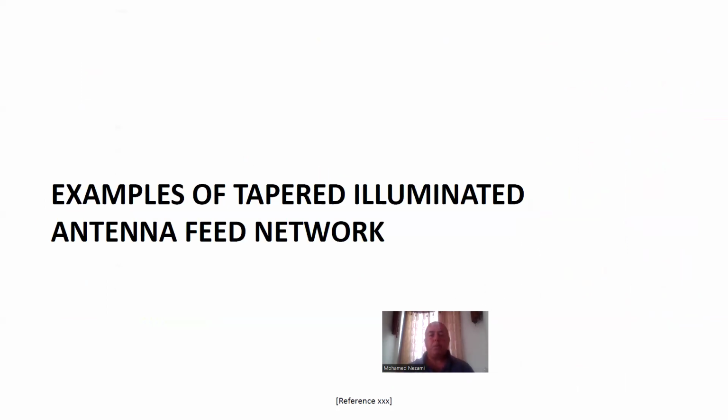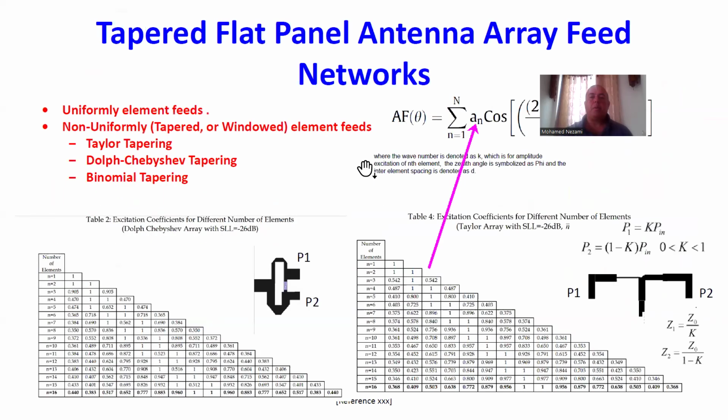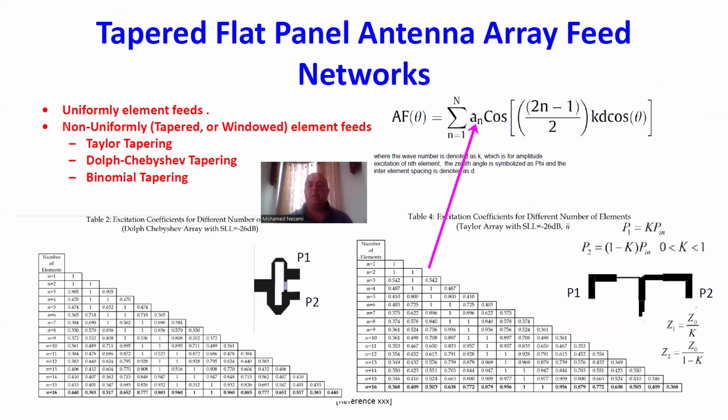And that's it. So for this session, we're going to stop here and introduce the next video topic, which is these here. Now, these are more complicated because we have to design individual power dividers based on the ratio of these powers in here, based on these coefficients. So we can say we want 0.96 dB, 0.69 power ratio to 1 to 0.96 between this and this, while between this and the other one is 0.87.